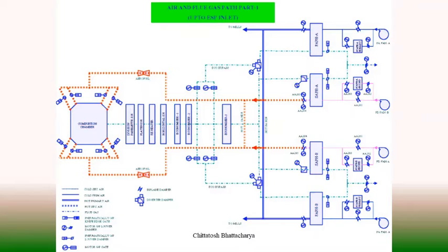These gas recirculation fans recirculate the flue gas partially within the furnace, and this arrangement is basically a part of superheater temperature control to minimize the availability of excess air and to dilute the total product of combustion, so that heat available for absorption is reduced. So this way we are having different fans.